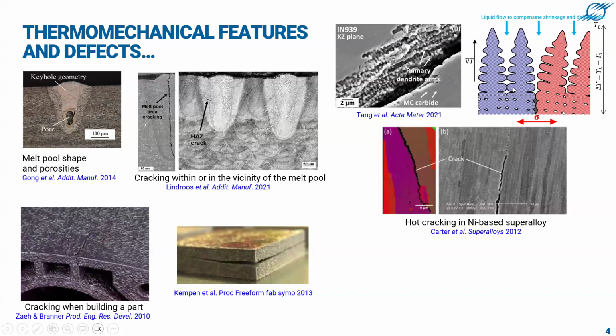In the last stages of solidification, where you have some dendrites growing in an epitaxial way from the previous deposition, and during this dendrite growth, when solidification is almost complete, some liquid films can be fractured, provided that you apply a certain stress perpendicular to the growth direction, I would say.